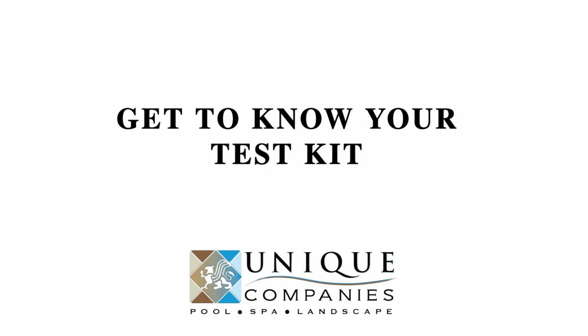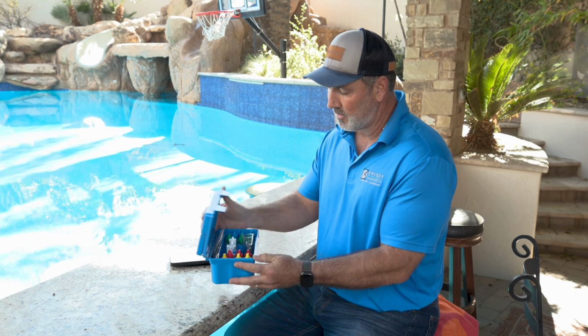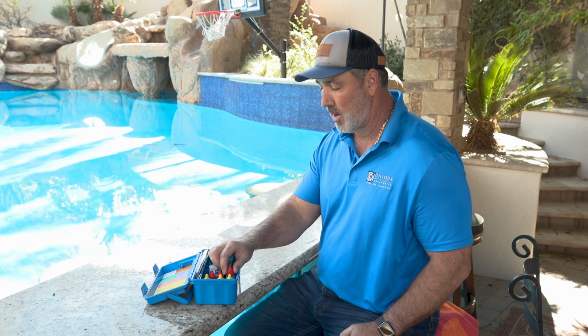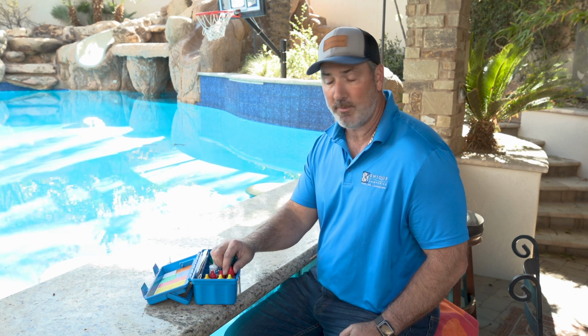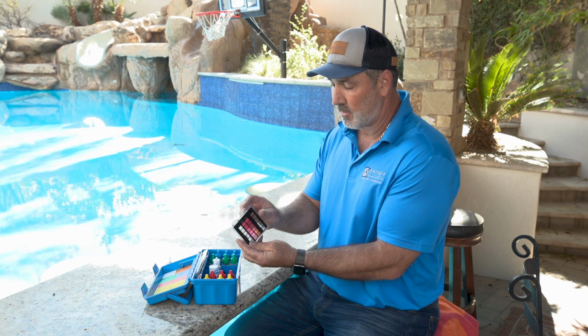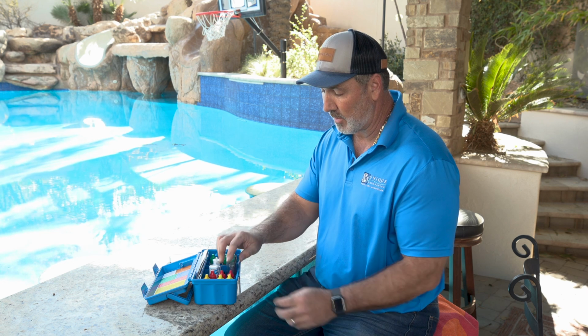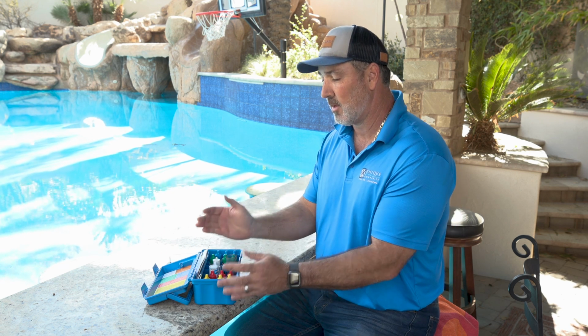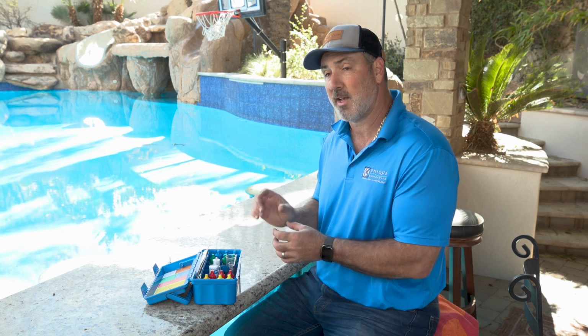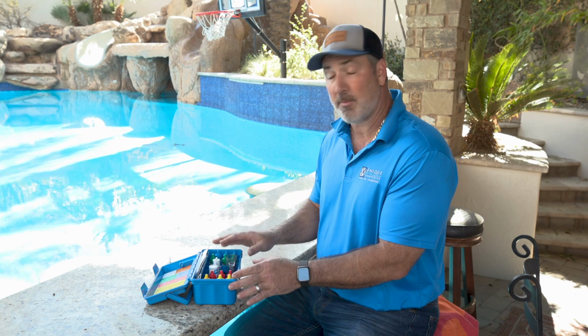First off, my startup team should have provided you with a chemistry test kit. Now this is a professional test kit that I use. The one that we provide you is a little bit smaller. It's got 3 different reagents in it so you can test chlorine, acid, and alkalinity. Inside this you'll have these little test tubes that you can mix the water and then get the readings. And we find that this is far better than the test strips.